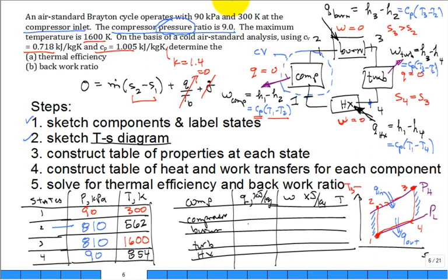All right, I was glad to see a lot of people have finished this problem out already. So it was 0, 0, 0, 0 for those. And then people were making the calculation. So it's C sub P delta T. That's what you're doing again and again through this. And so we came in with negative 263.3 on the compressor work, and it's a negative because I'm going to sum that column, and I want it to work out that way.